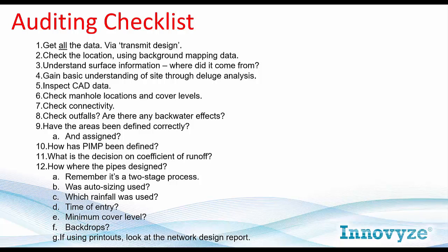Secondly, check the location of the study. We have this ability now to use Google Earth, Google Maps, other sort of mapping data just to make sure we're in the right location, so that's crucial just to get a feel for the site, and also the fact that rainfall varies across the country, so you need to be in the right location.